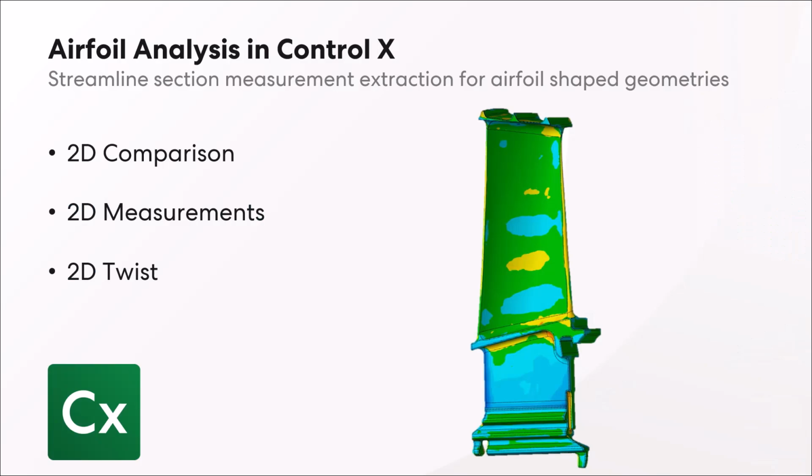In addition to the simple 3D compare between the reference and the measured model here on the right side, with this set of tools you can extract dimensional information specific to airfoils, such as a 2D comparison between the reference and measured section through the blade, 2D measurements for airfoil specific features, and a 2D twist analysis to evaluate the blade profile without the deviation along the blade axis, the twist angle and the displacement along the section.